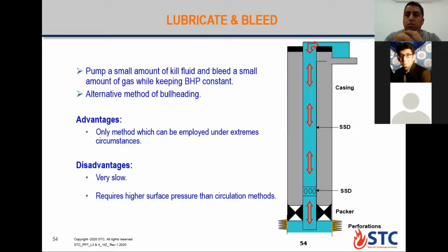Okay. If we have a non-compressible or slightly compressible fluid like oil in the well, then it would be difficult for us to pump inside the well. If we don't have any injectivity or intake from the reservoir, it would be difficult to compress the slightly compressible fluid inside the well. It will be a little bit difficult. That's why I said this method is especially for gas wells. It is easier with a pure gas well, but we can use it in oil and gas wells also.